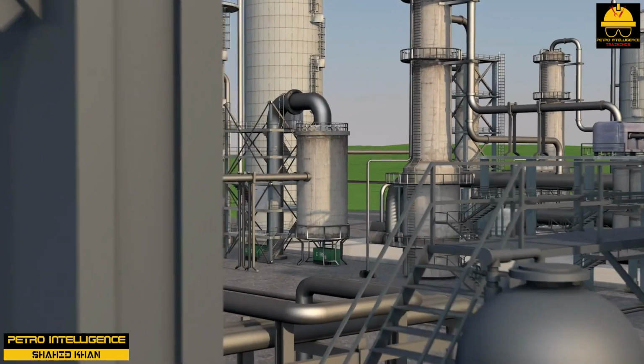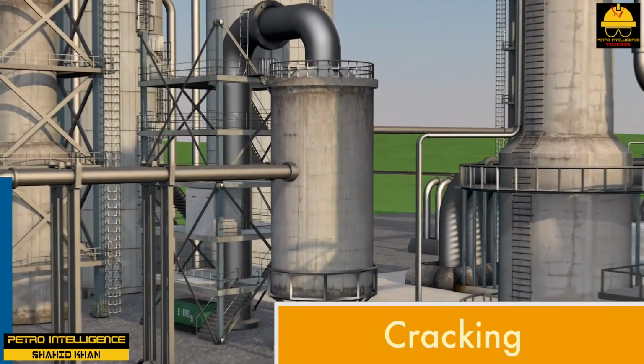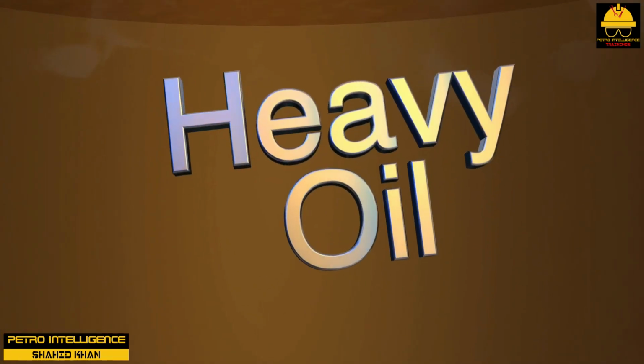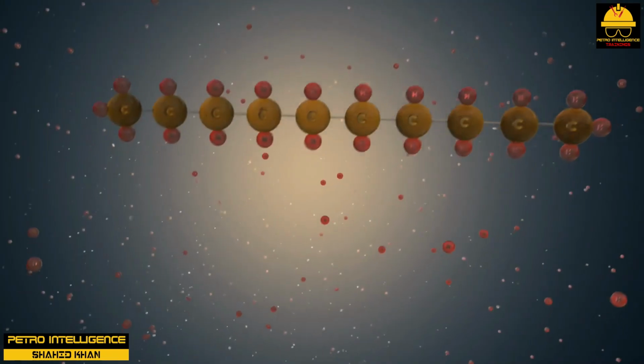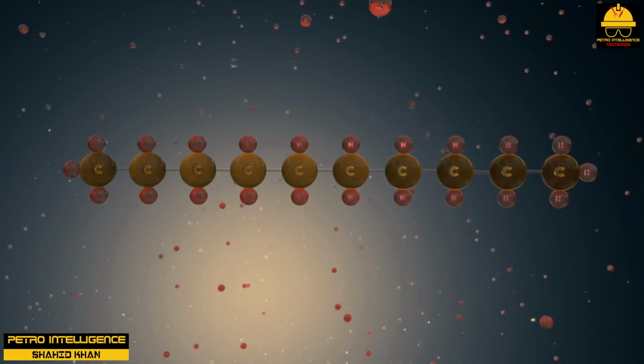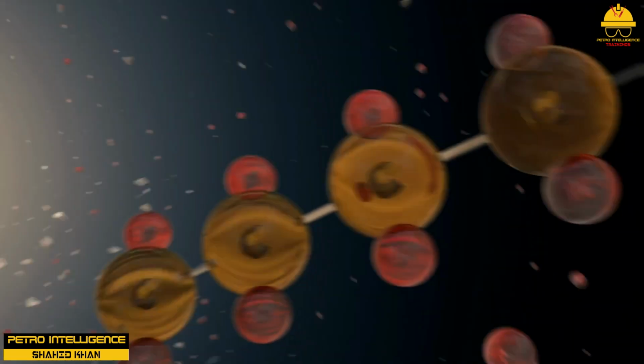Hydrocracking. Hydrocracking is a process that industrial manufacturers use to boost gasoline yields. The process takes heavy gas oil molecules and splits them into smaller, lighter molecules called hydrocrackate. During operation, hydrocracking units use a first and second stage fixed bed reactor, a separator drum, and a fractionating tower.